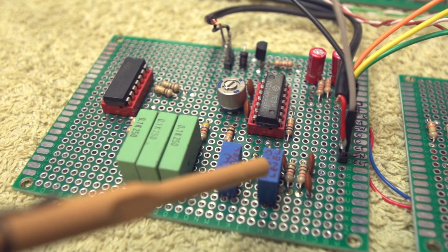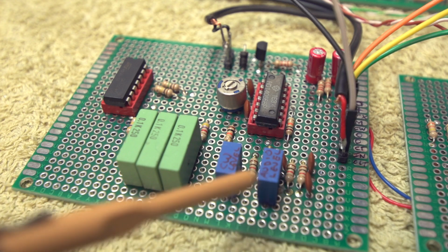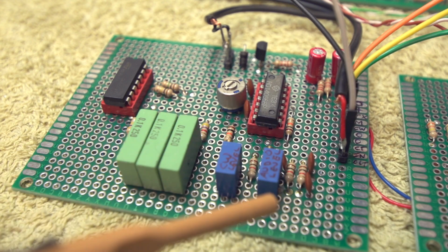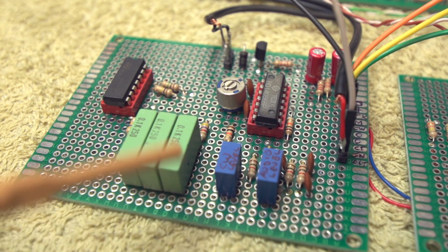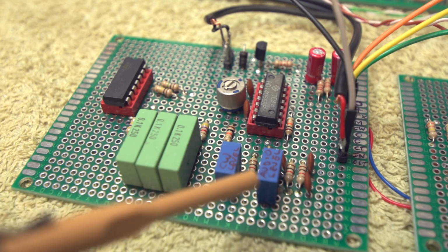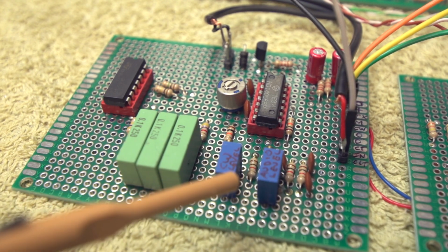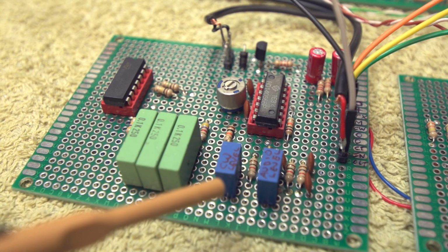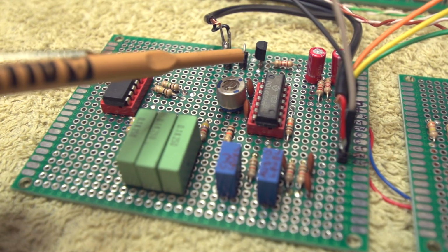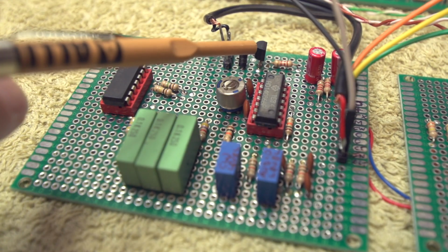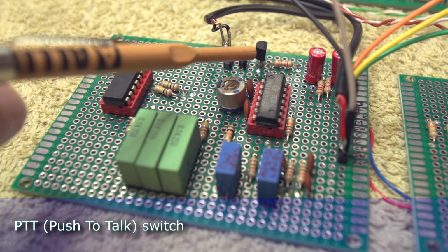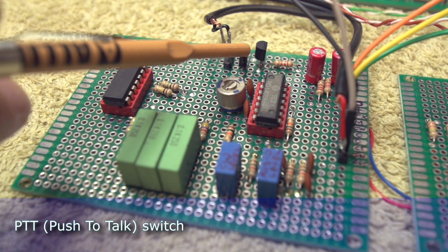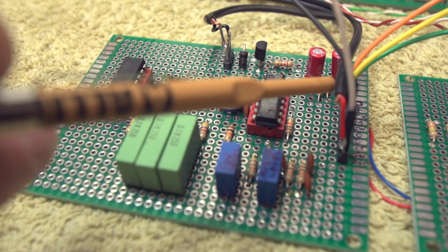So with these 3 controls, and these 2 are a little bit interactive as well. It's a very simple resistor mixer. There's nothing active here, so the resistors do actually affect each other. So you need a little bit of fiddling backwards and forwards, but eventually you get it balanced out and it sounds correct. This little bit of circuitry at the back here, it's just a key-in transistor, which basically turns the transmitter on and off, again from a signal from the control card.